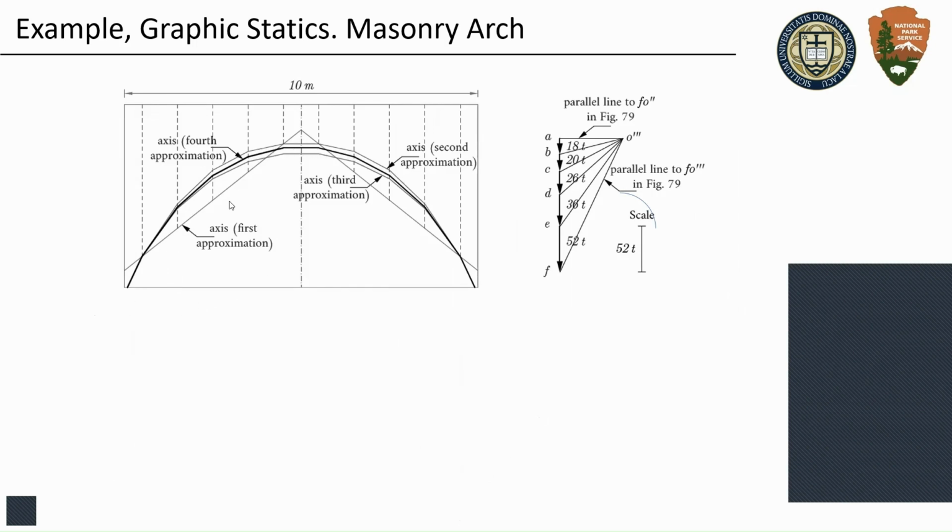So we started off with the first approximation, we calculated the weights, we hang the weights from a chain, we flip it around, we calculate the weights again on top of that chain that represents the arch, and we continue the process, and it quickly converges to my arch. So it's a very powerful tool, and we know for sure that this is under full compression under these particular loads. And again, this is parallel to this one, and this is parallel to this one.